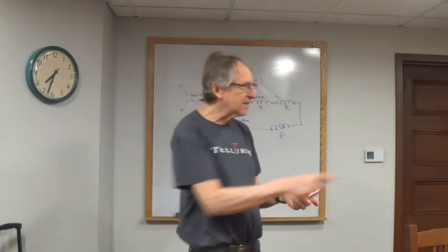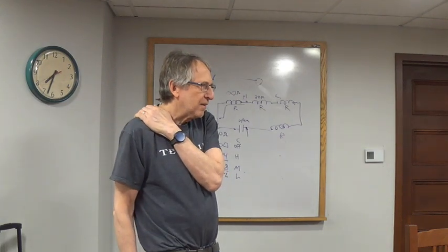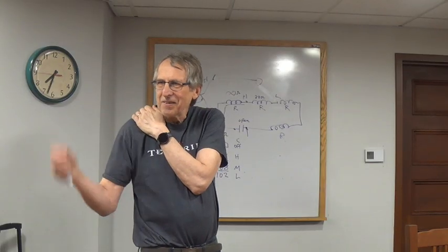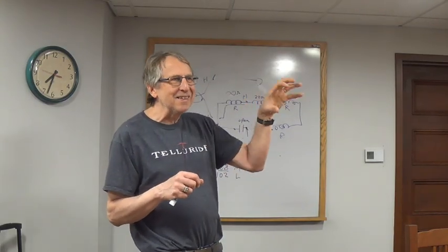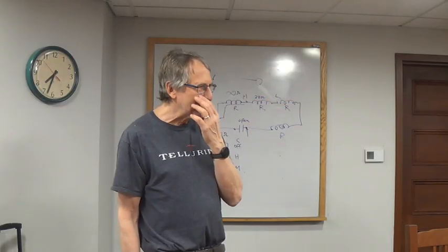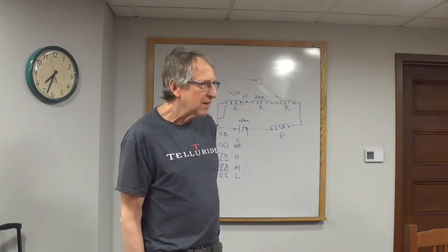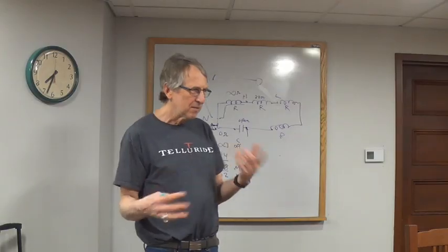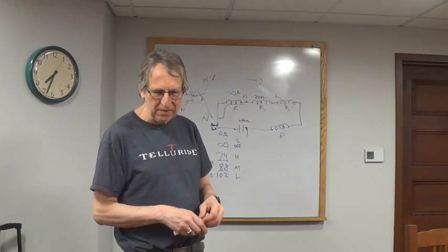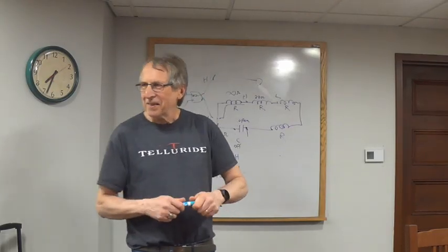And the last thing is the capacitor may have failed. To be fair, I have miswired ceiling fans and turned the switch on, and the capacitor makes this hissing noise and there's smoke. So it's possible that the capacitor is bad, but typically if your fan isn't working, it's probably not the capacitor, it's one of the earlier things. Could be that it just sat around for too long, or you didn't check the fuse in the plug.